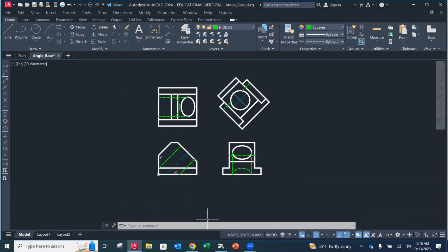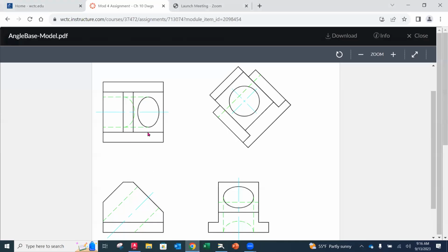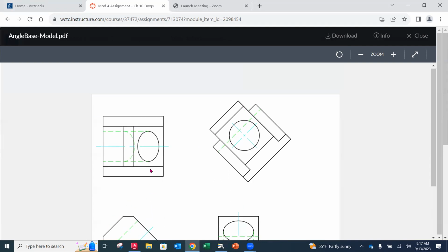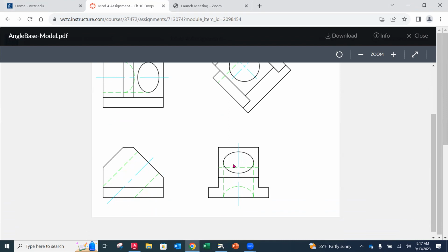Now there are some center lines to put in here. I'm going to peek at our guide. So I'll get rid of that hidden line right there. That's not supposed to be there between the circle. But I want you to add in a center line just going horizontally here through. We don't need to add a crosshairs going up on an ellipse. Okay, we're just going to show the line as it's going through. Same thing with the right side view, just a line going straight down. Okay.